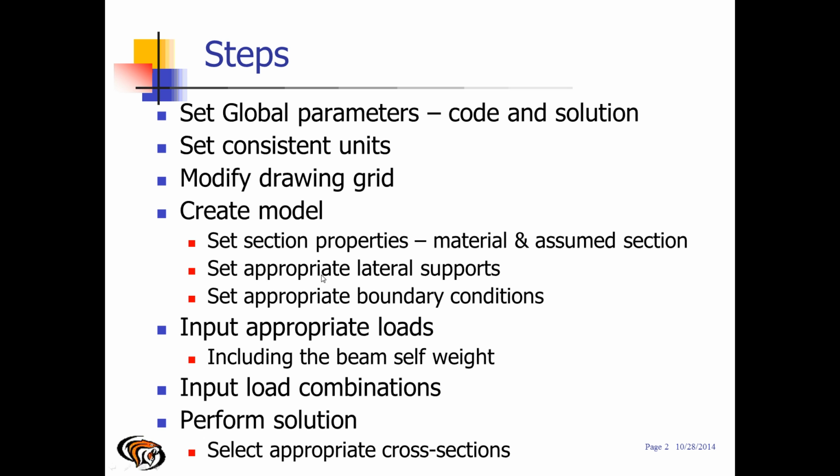The lateral supports will be set here. This is a little different than what we've done in previous videos. Then we'll set appropriate boundary conditions. Finally, we will input the loading. Here we will include the weight of the beam. The last item is do load combinations and perform the solution. In the solution, we will ask RISA to conduct the appropriate optimization.